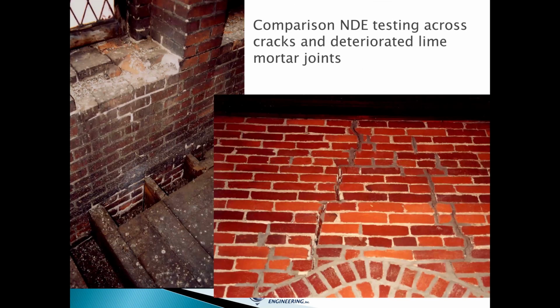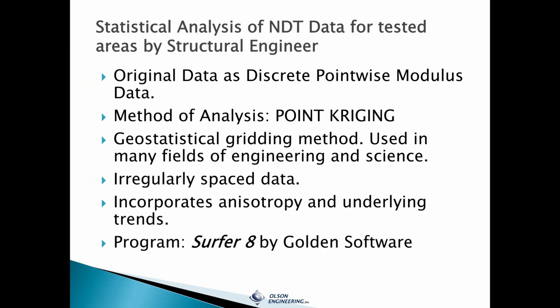Okay, so the structural engineer was doing this, more senior, in his early 50s, getting a PhD at Cornell, and he was doing this to help the church out as well as part of his PhD dissertation. A very good structural engineer, very experienced, and he had done a lot of work on masonry, and he applied this discrete pointwise modulus data with a point kriging analysis, and that handles irregularly spaced data.